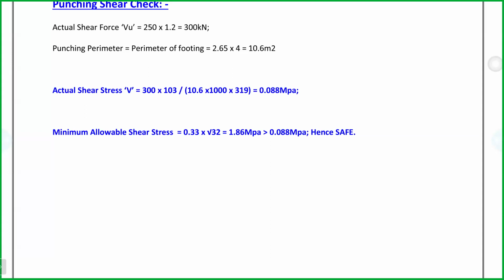But what about the spacing? Spacing, yes. In constructability, as I told you, we go for spacing starting from a minimum of 100 millimeters. We'll never go for odd numbers like 80, 90, 70. Okay, 100, 125, because I cannot give you 110 or 120.